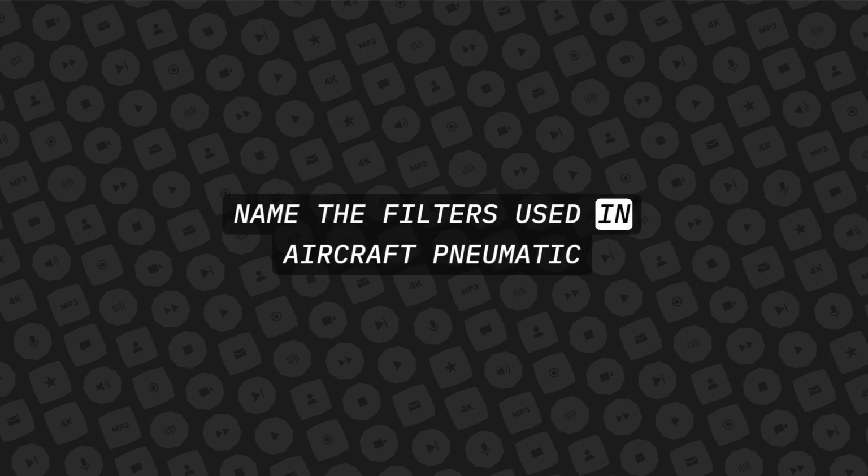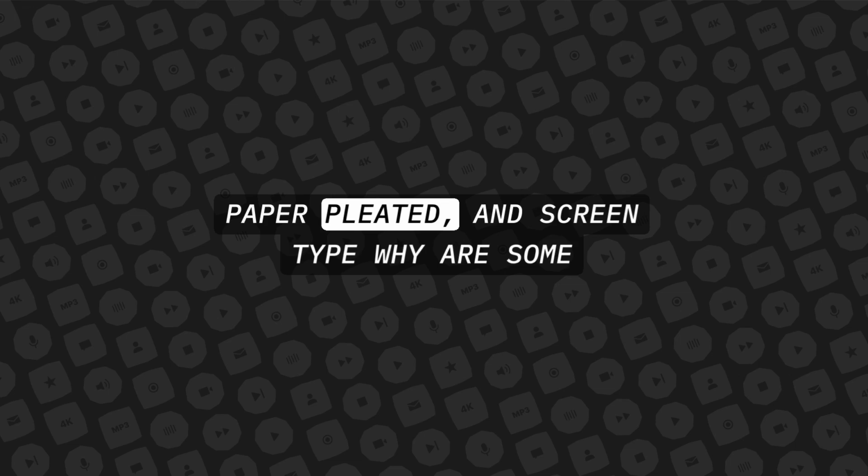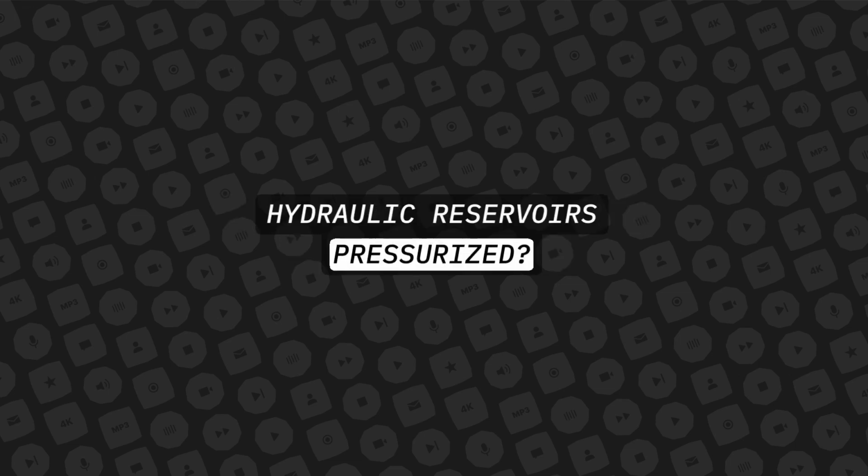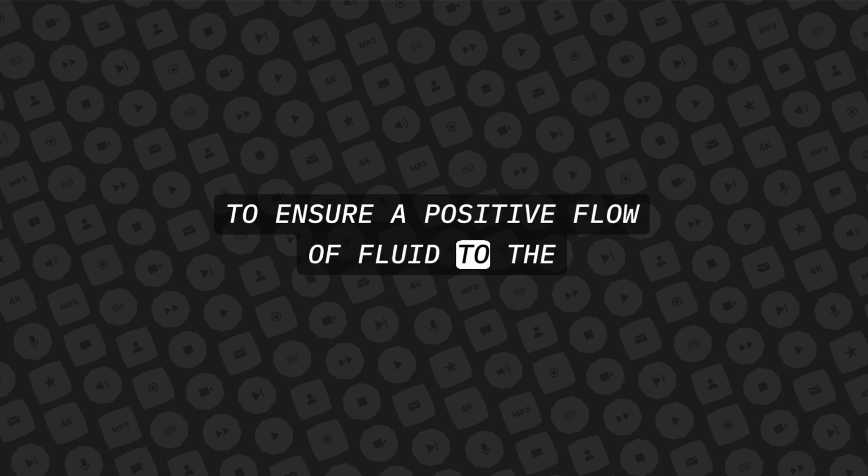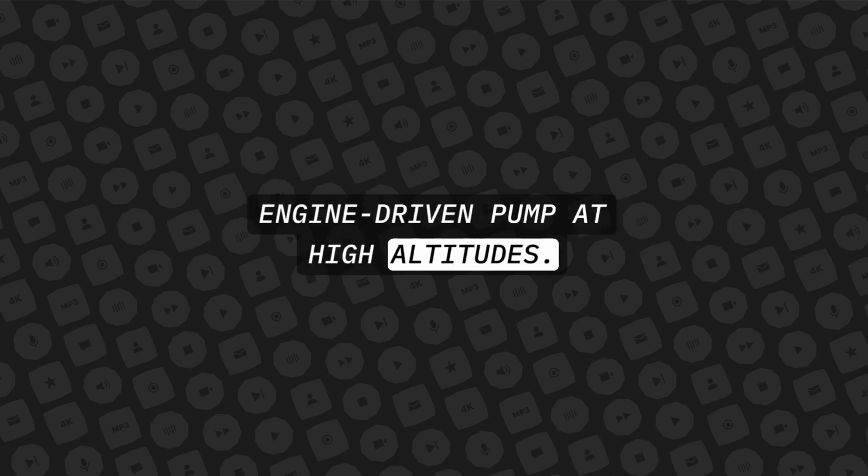Name the filters used in aircraft pneumatic systems. Paper, pleated, and screen type. Why are some hydraulic reservoirs pressurized? To ensure a positive flow of fluid to the engine-driven pump at high altitudes.